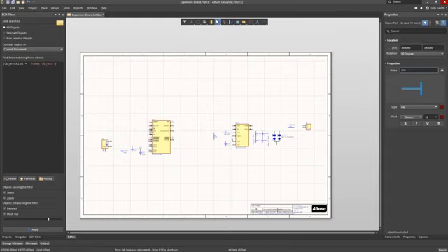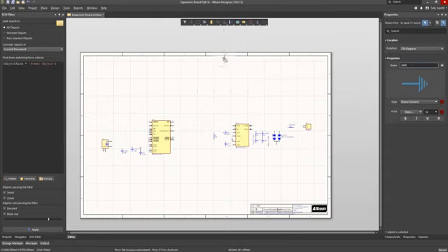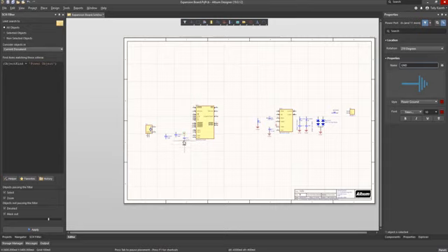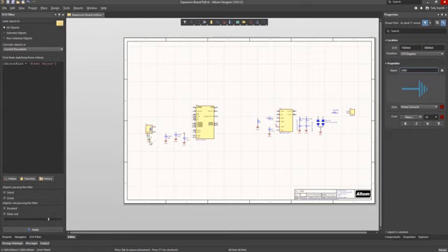Right-clicking again on the ground icon in the active bar menu, we can select the port GND. One thing to note, the tool remembers the last used port, aiding additional placement. This helps to continue placing the needed ground ports. We can add a wire automatically by selecting the port and moving it over to the component and placing it directly onto the pin. Then, by holding the Control key, select and pull away the power port to auto-create a wire.